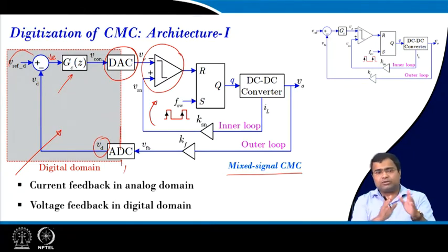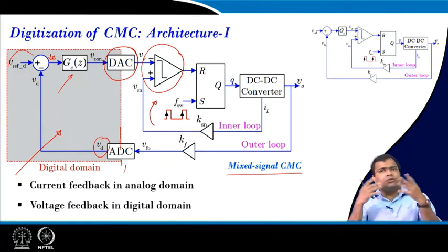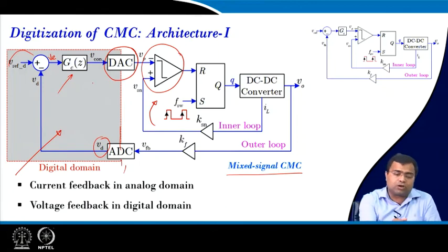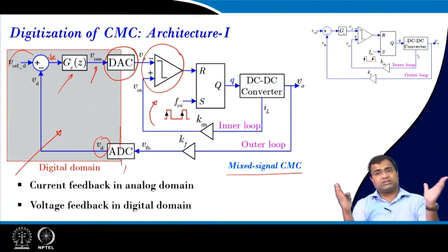Because we have discussed in the previous lecture, if we take one sample per cycle where there can be delay, then the voltage loop will be updated once in a switching period, and that means throughout the switching period it will be constant, and then the controller will also be computed in synchronism with the clock. So, the controller output will also be constant for the whole cycle.